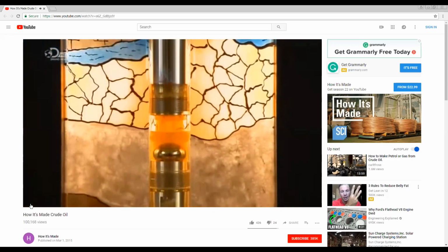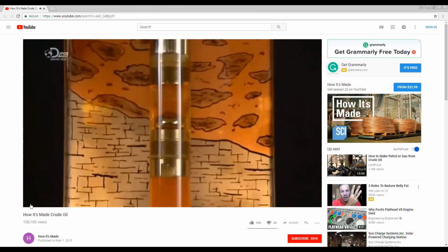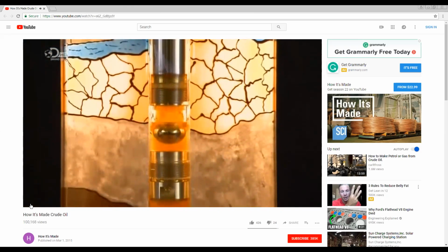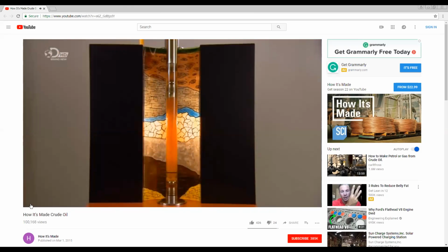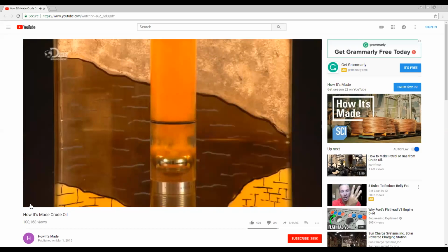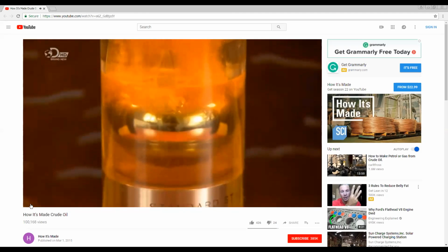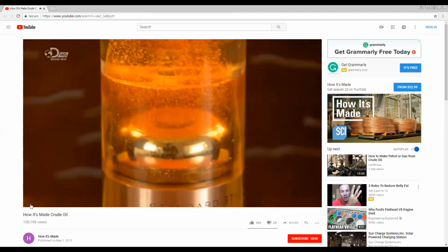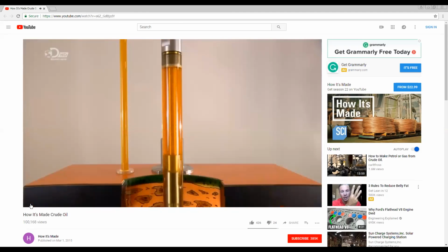Here's what goes on inside the well. With each downstroke, the pumping unit pushes a steel rod down the steel tube lining the well. With each upstroke, the rod rises, and the pressure difference between the fluid on the outside and the fluid on the inside opens a ball-shaped valve, blocking the bottom, letting the fluid flow up the tube. Another valve at the top releases the fluid out of the well.